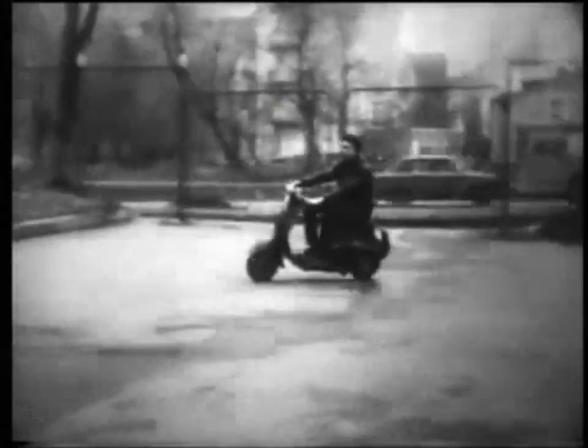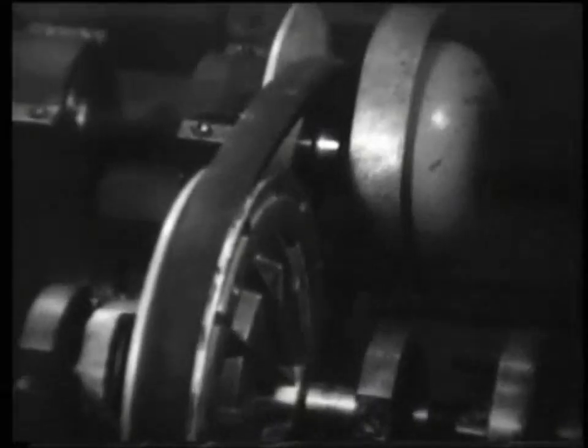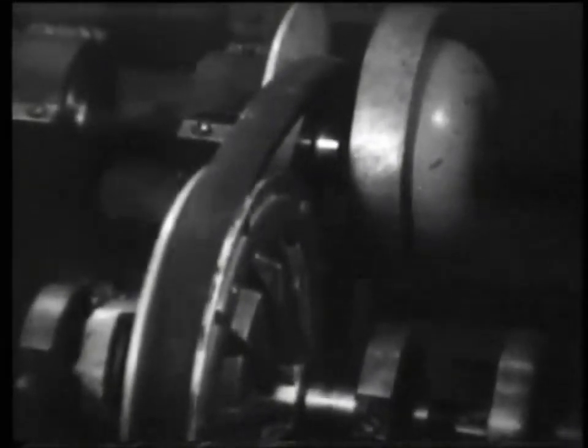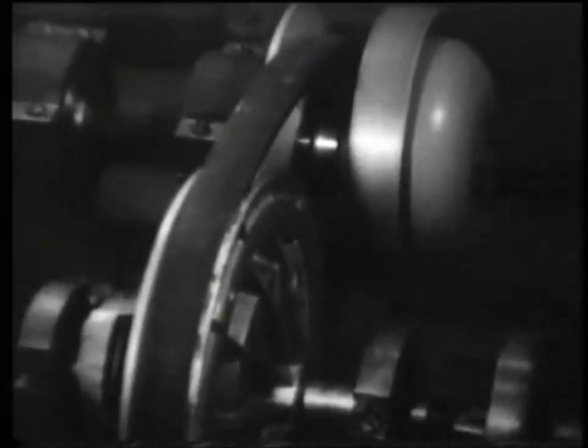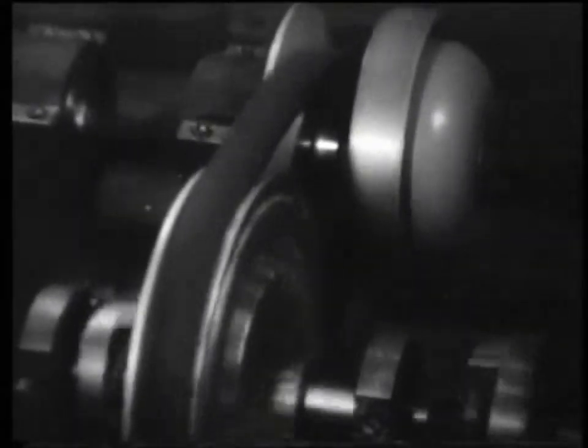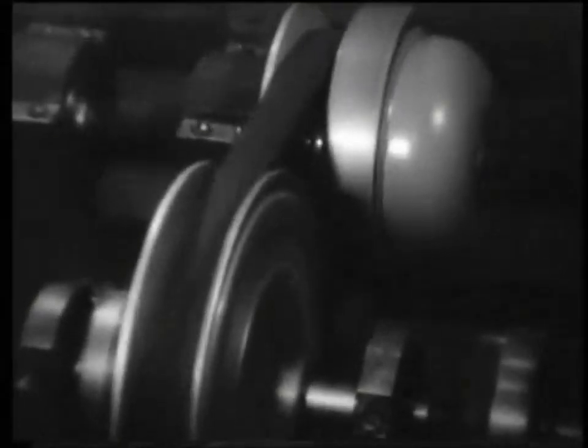Wide belts of special sections are used in variators of motor vehicles. Scooters and snowmobiles with such variators do not need a clutch. If the variator is turned off, the drive pulley discs are pushed apart and the belt lies on the bearing or shaft. When turned on, the variator first works as a clutch, and then as a belt drive at the highest gear ratio. Moving the discs adjusts the speed.